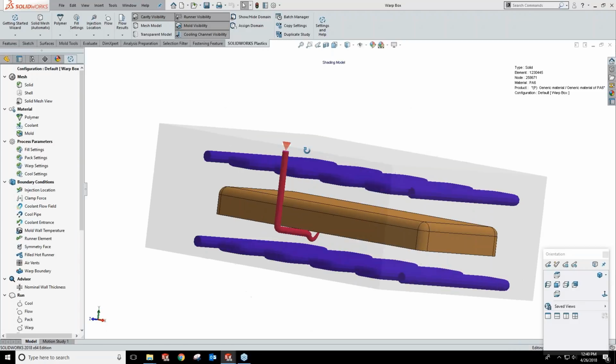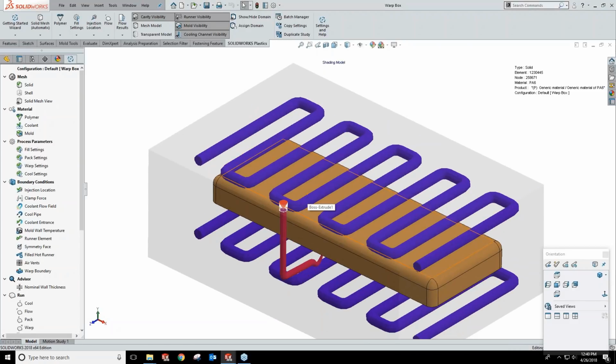So whenever you can, again, speaking from working backwards on it, if you have multiple cooling lines and you're having a problem with a hotspot, you can model the cooling lines if you have the mold drawings or the 3D CAD file, and you can put a lower flow rate on those cooling lines and simulate the hotspots you're getting, and you can have a good idea of what's happening there and what you need to do to fix that problem.